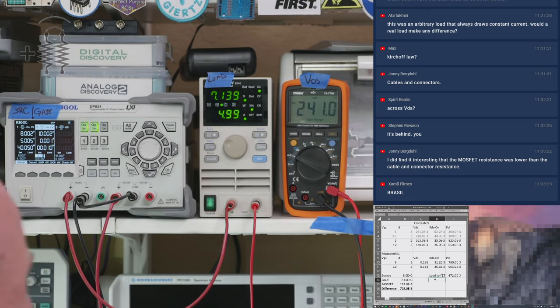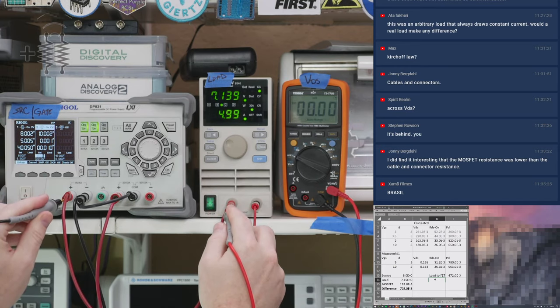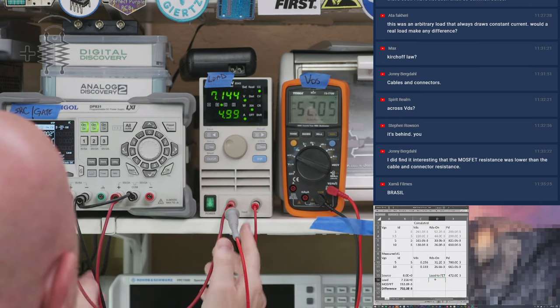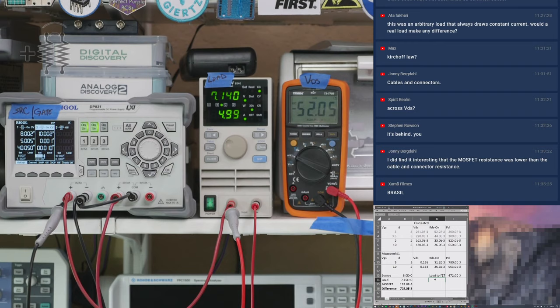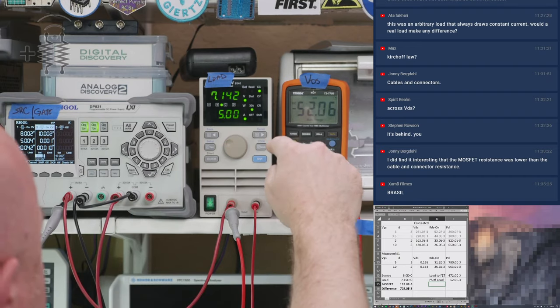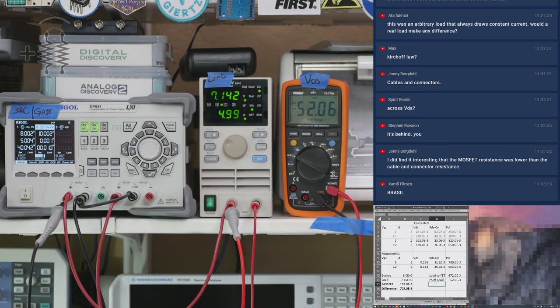Now let's measure from, this should be a good one. We'll measure from the power supply to the load. There's another 52 millivolts. Okay. And then let's see, power supply to load, load to the FET. What else do I got?